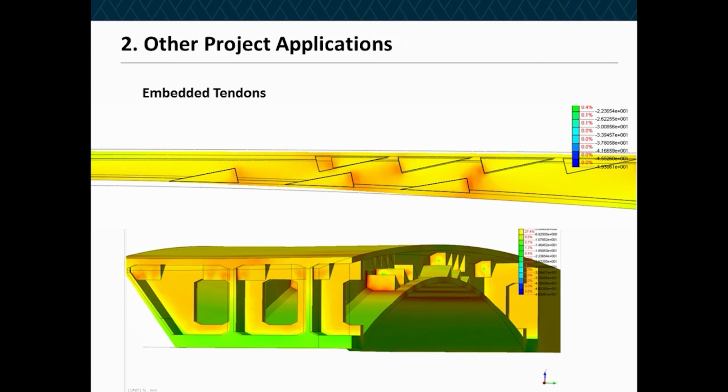But anyway, the whole thing was modeled in FEA in solids, and we used embedded tendons, which is another function within MIDAS. Okay, you can just about see those different colorations on the faces of the blisters, and that's where the tendons terminate. So that's where you get your stress concentration in the blister block.